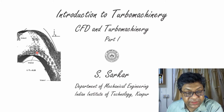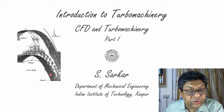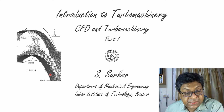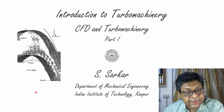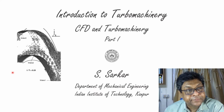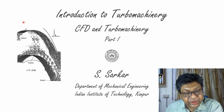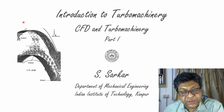the blade passage. And this wake will interact with the boundary layer forming on the suction surface, and thereby periodically excites the boundary layer. This kind of flow is called wake-induced flow. So here the flow is highly unsteady and three-dimensional. With this motivating picture, I'm starting the chapter CFD applied to turbomachinery.